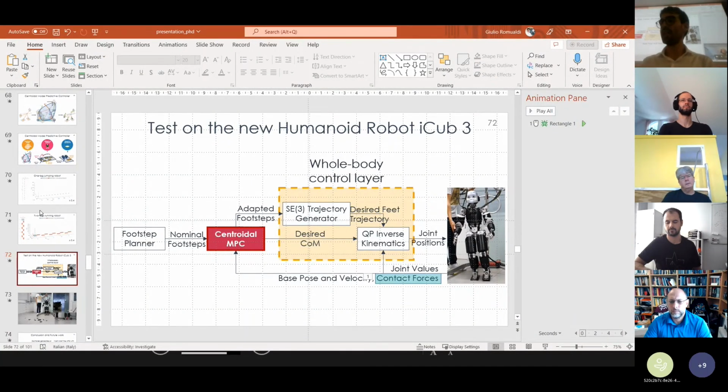Also, I think on iCub, having a controller that considers a tracking error on the joint torques, because we know that we have it, could probably be a possible future direction in order to improve the high-level torque controller on the robot. Because what we have right now assumes that the torque that you require is the one that you get from the robot. But on iCub, this is not the case, at least.